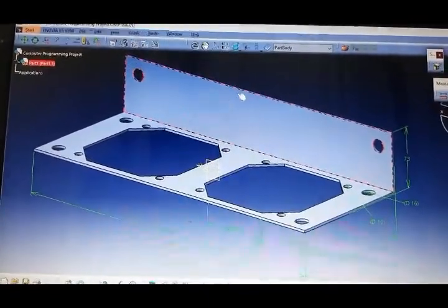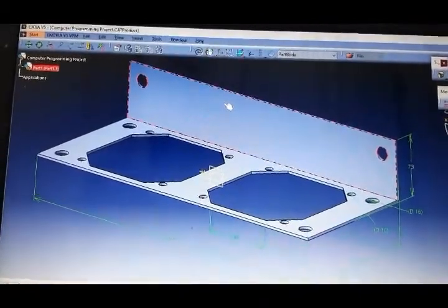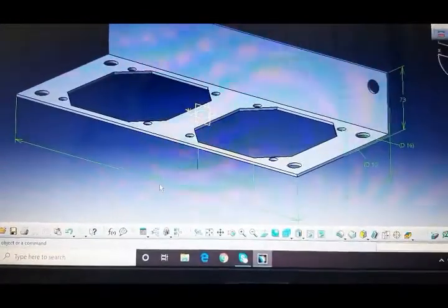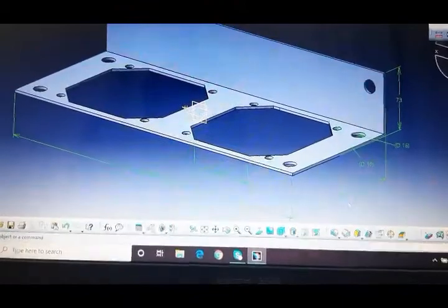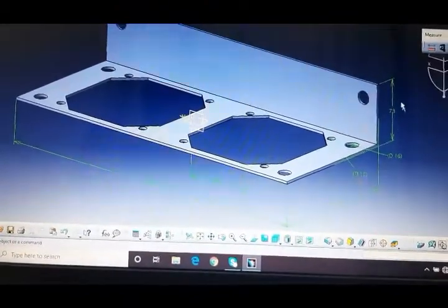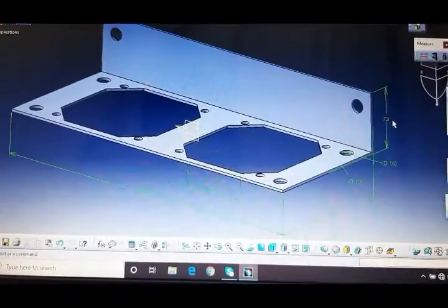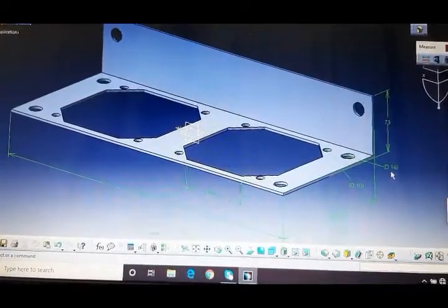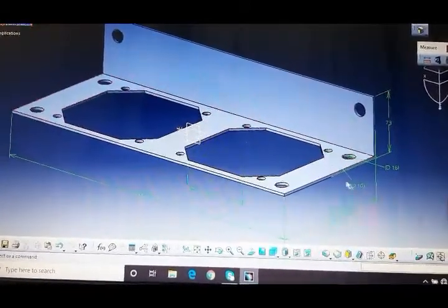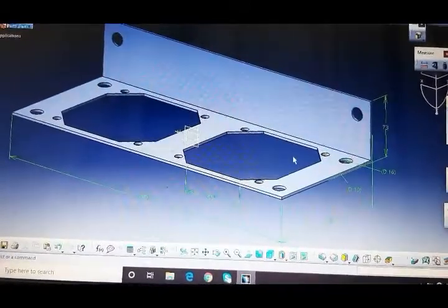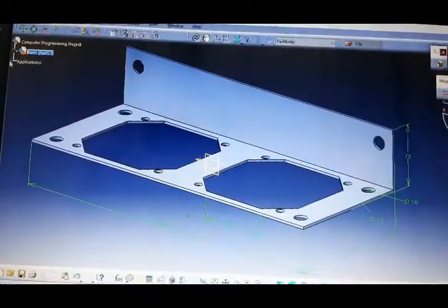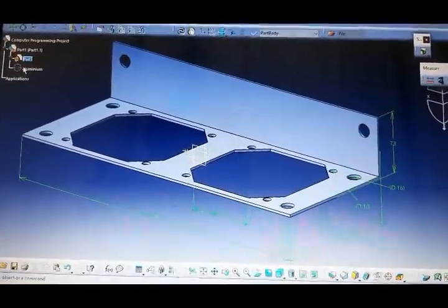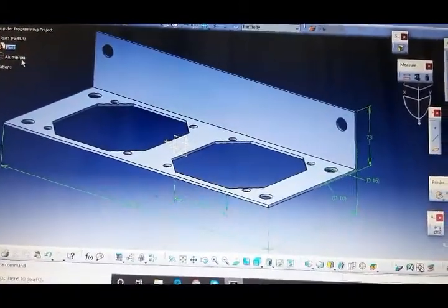Firstly, we must cut and shape the plate, then make holes in it. The product length is 400 mm, the width is 163 mm, and the height is 73 mm. The big hole diameter is 16 mm, while the small hole is 10 mm. Then we apply an aluminium material to the product because it is easy to bend.